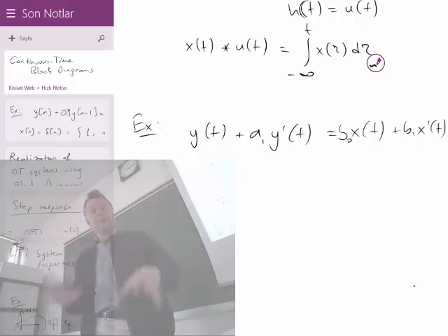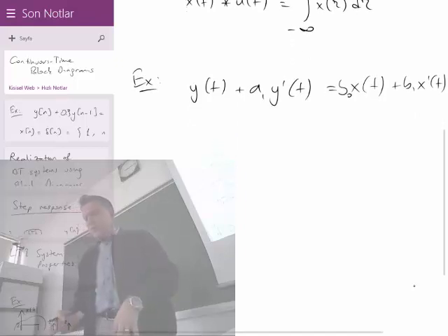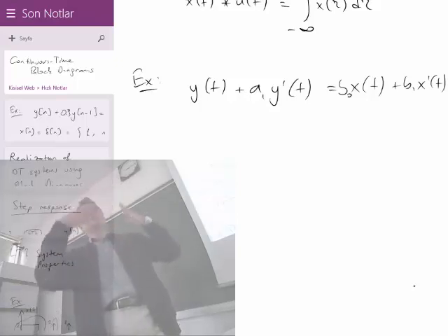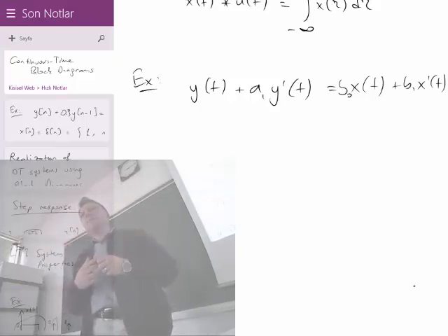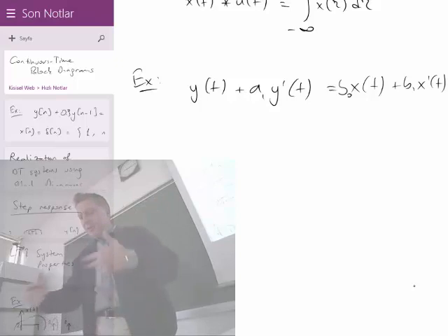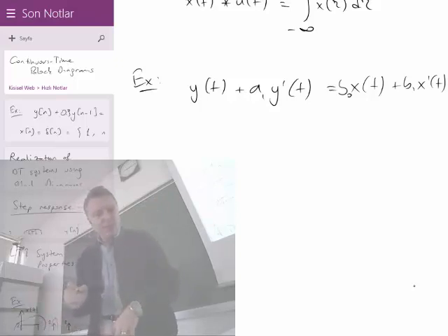block diagrams in general. What you're going to do is integrate both sides of the equation once, so that both sides of the equation will have a minimum of the signal itself, not its derivative, not its second derivative, not its third derivative. It will have the signal and its integrals, which will correspond to cascaded outputs of that unit step response system. So let's integrate both sides of the equation, and we are going to give